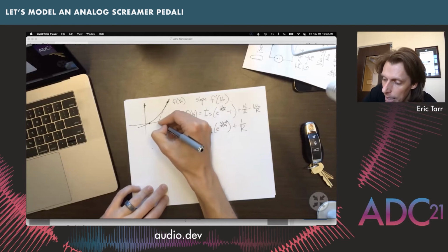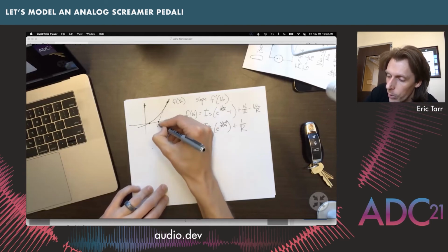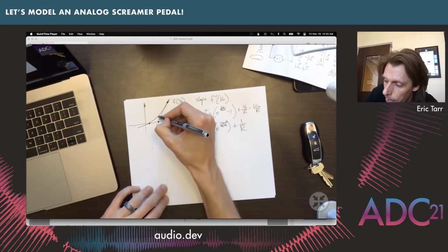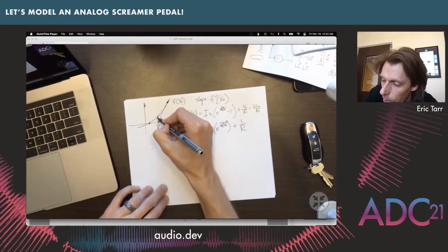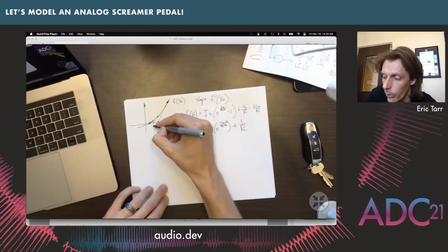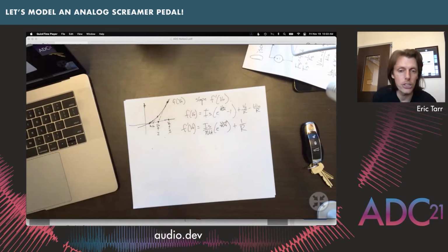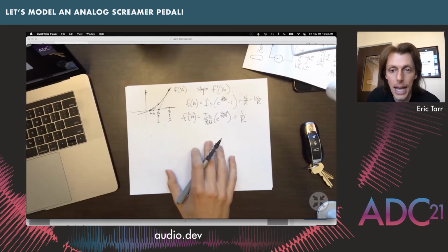Then we'll move out and we'll try this as our new V out value for guess 2. Okay. And then we'll be able to get some new things here, a new slope, and eventually we'll be able to move down until we get within some range and we say, okay, we're good enough. You know, we've moved V out closer and closer. Maybe that only took 3 iterations or 4 iterations to make that happen.